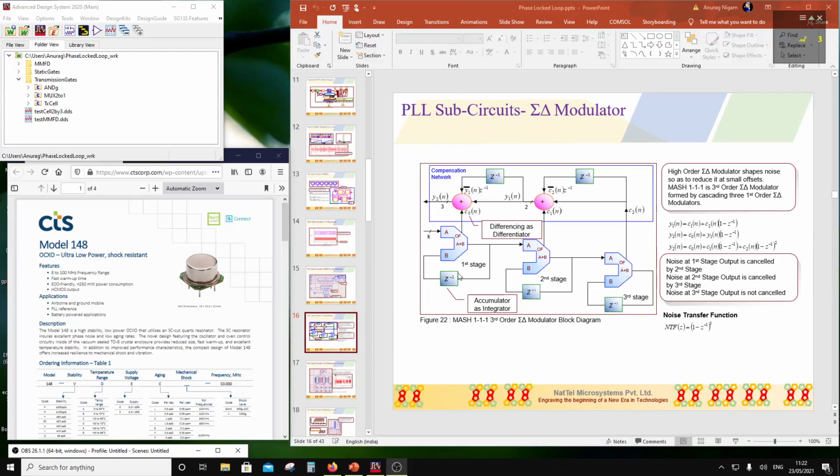Now here I'm going to first design a 1-bit accumulator, and then I will do a 12-bit accumulator here, and I can do a 16-bit accumulator if I want, but because this circuit operates at a lower frequency, you have to run through that many 2 raised to n cycles for this PLL to stabilize, right?